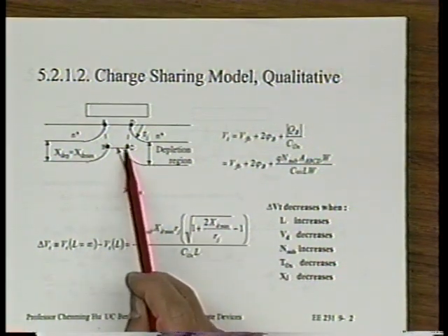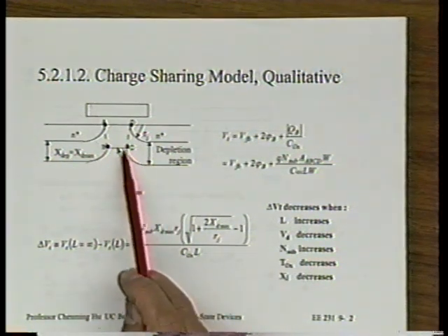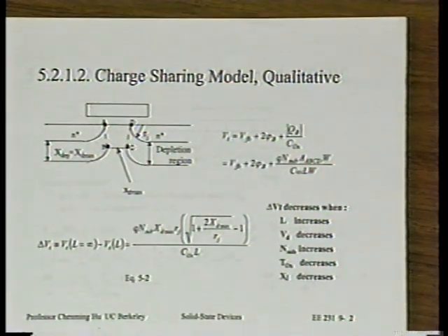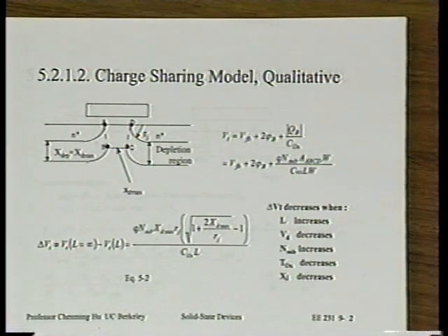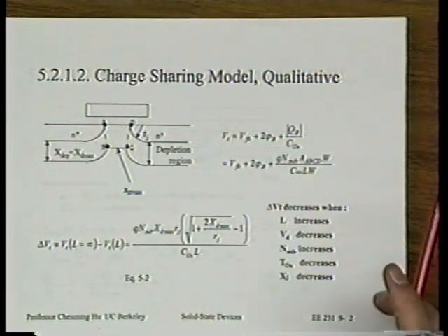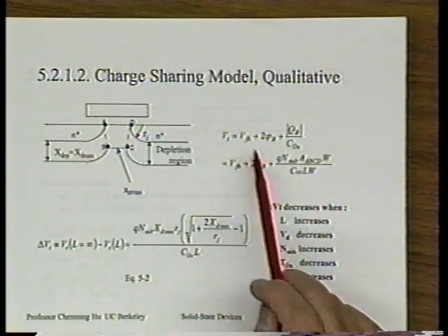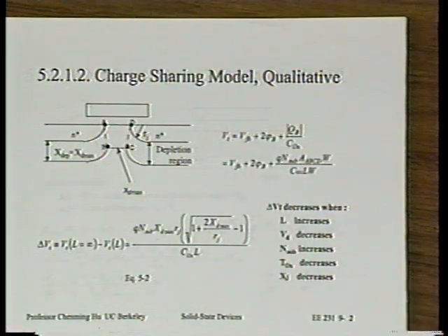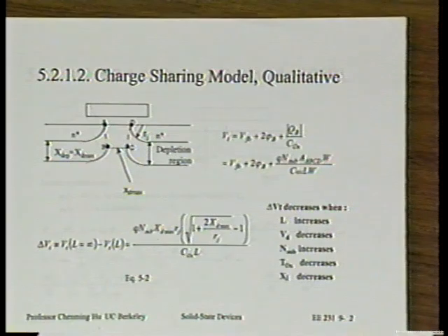Similarly, C is determined by the intercept of the channel depletion region boundary and the drain depletion boundary. You visualize that? That's the result. We now have four points, A, B, C, D, and they form a trapezoid. Is that okay? Next, the model goes on to argue this way. It says the basic model says Vt is equal to VFB plus 2 phi b plus the charge in the body over Cox.